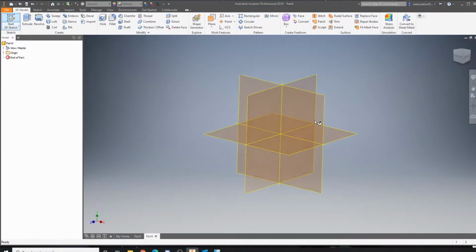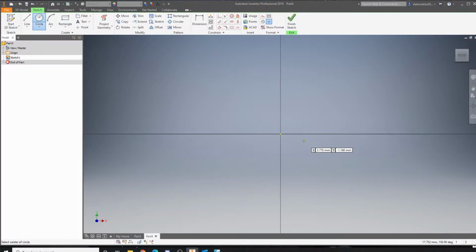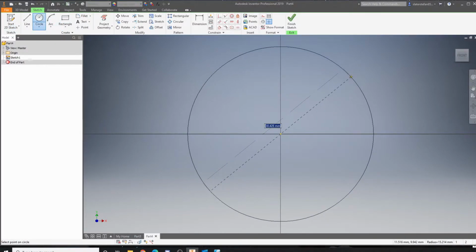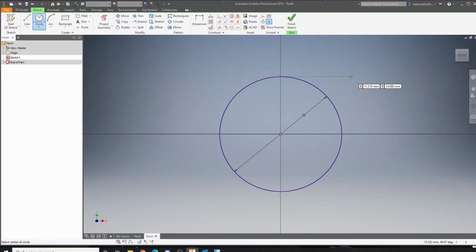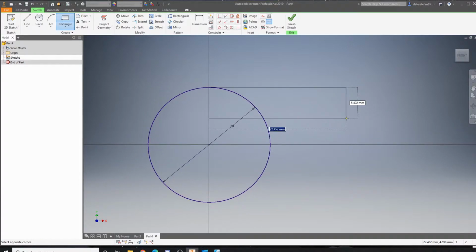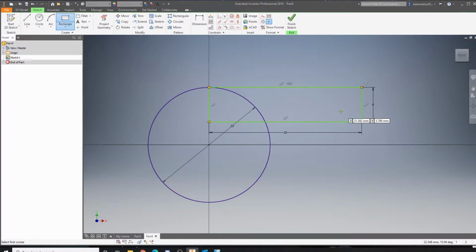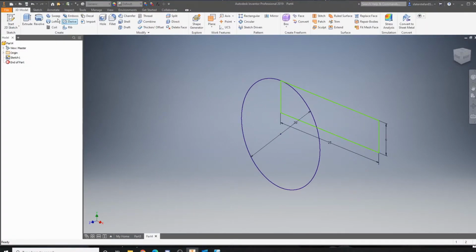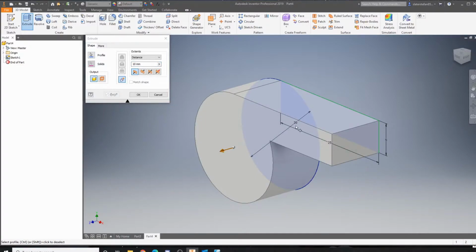So we'll start a 2D sketch, click on the work plane. I'm going to draw a circle right on this cross axis at 20. I'm then going to draw a rectangle that is touching up here, and this is 25. I'm going to click tab, which is next to your Q key, sometimes next to the 1, and that lets me change right to there, and this is 6.